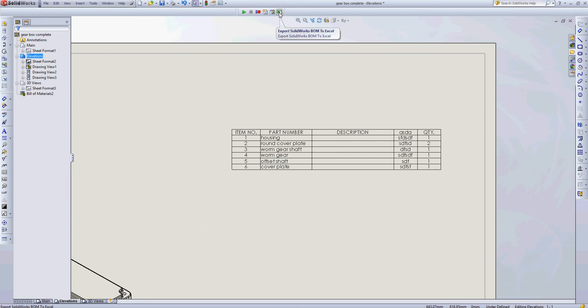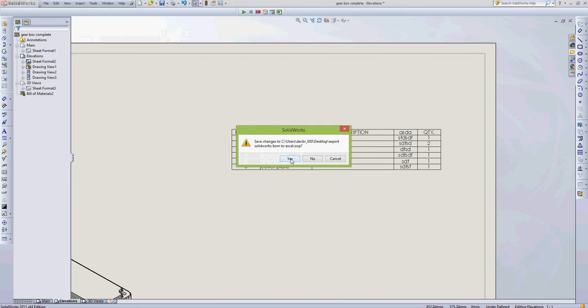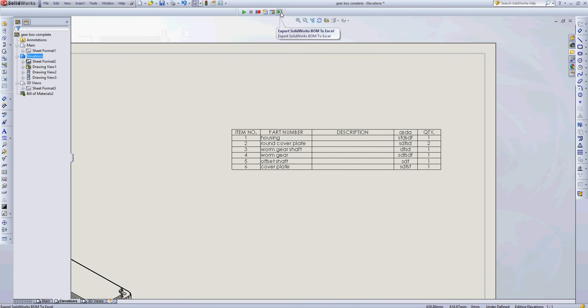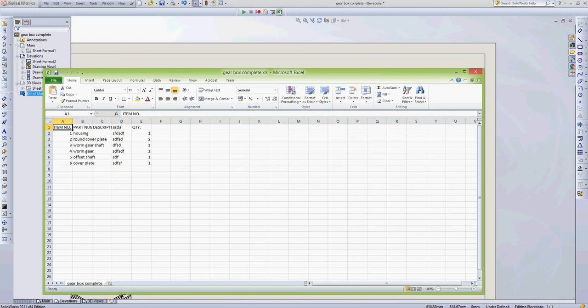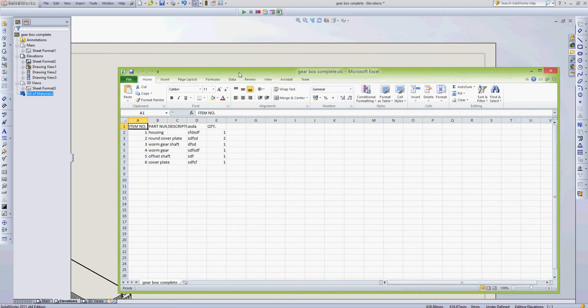As you can see, the prompt helps users to know what the button's for. Okay, so now you can actually run this from within SolidWorks. So you can close the Visual Basic Editor down. I can just save that. And then now if we run it, okay, so there you go, that's run, and it's running from within SolidWorks. So it looks like it's part of the software.